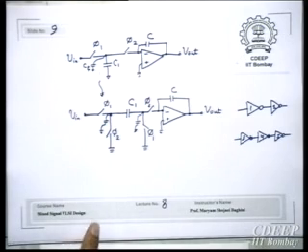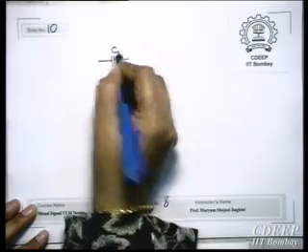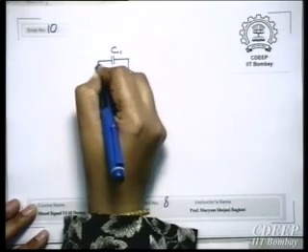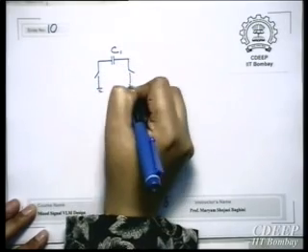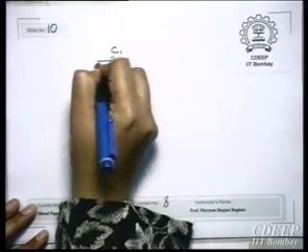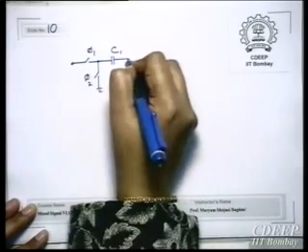And similarly for forward Euler and backward Euler. Again, you have this capacitor C1. We wanted to discharge it at phi 2, so we connect it to ground and we discharge it. And then in phi 1, it will be directly connected.